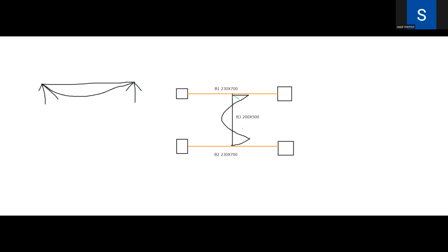Now, for example, in this beam we are getting the diameter of bars as 16 mm. Now we have to lap this 16 into 50, so it is roughly around 800 mm. This is for ordinary detailing; although for this secondary beam, we are going for ordinary only. So we are getting an 800 mm development length.